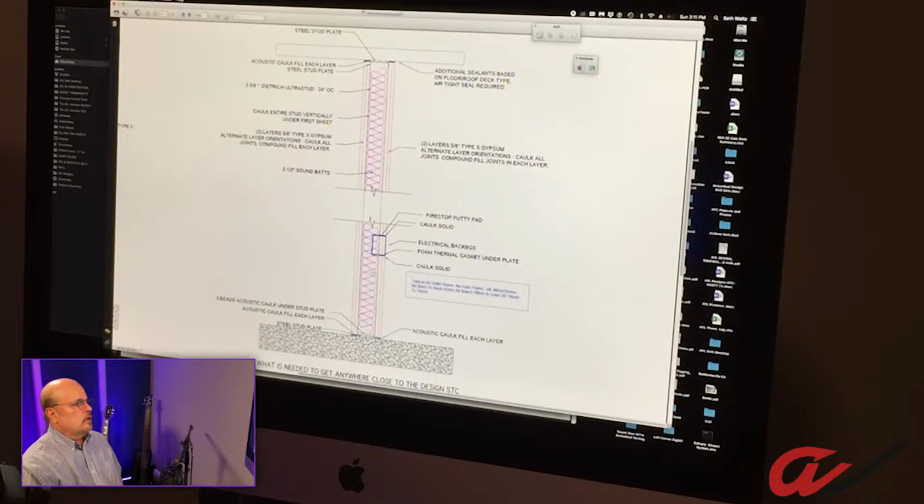The other thing you've got to look at is what kind of insulation am I going to use? And there's a lot of stuff out there online about this. Bad insulation, standard fiberglass, is what most people get. And with that, you need to get an acoustic batt insulation. There's a lot of people who make them. They stay filled in the cavity better and they tend to not settle as much. But fiberglass insulation does settle. So over time, you're going to have a gap at the top. You might have gaps elsewhere.